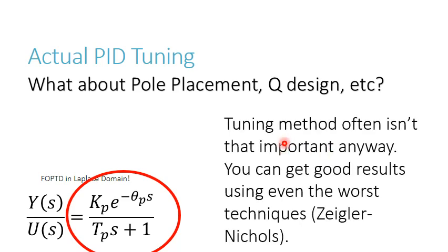It also happens that with tuning methods, even the old ones like Ziegler-Nichols or even trial and error, the technicians in the field are clever people, and they get excellent results. They get very low response times. They get very low overshoot. They know how to tune these things just by trial and error or Ziegler-Nichols, and so tuning method ultimately isn't that important in a lot of applications.